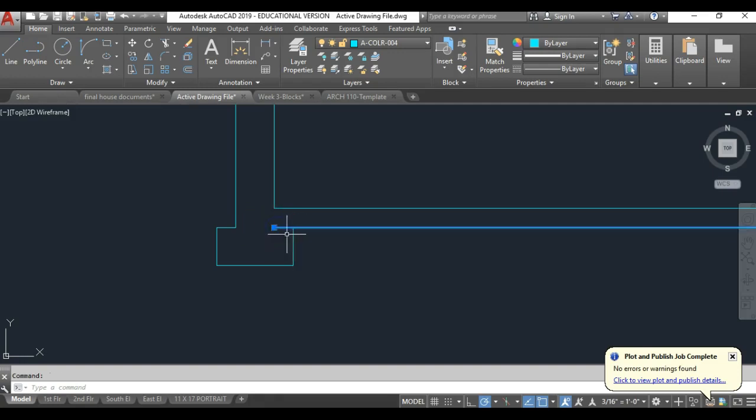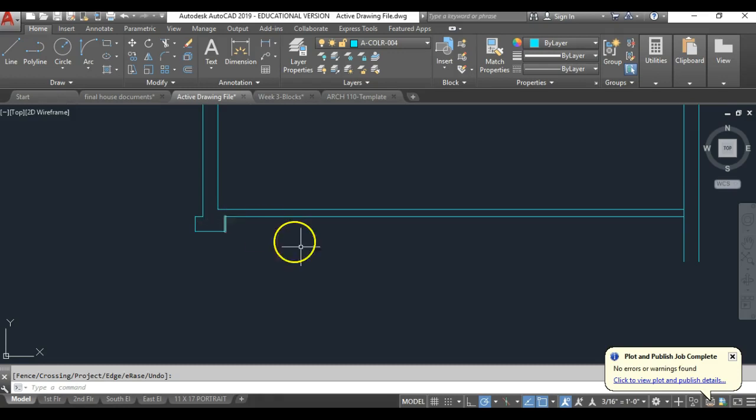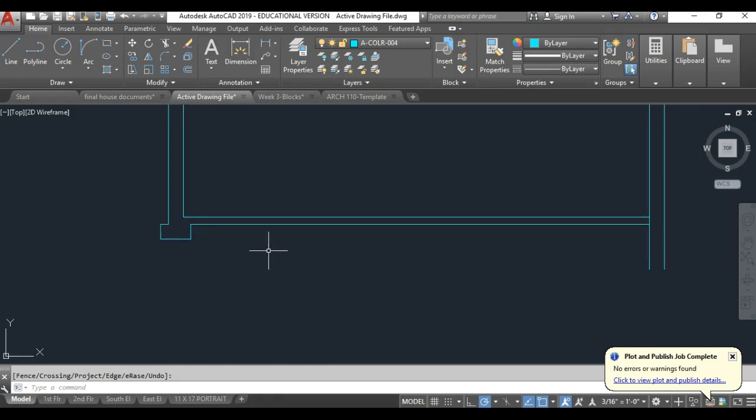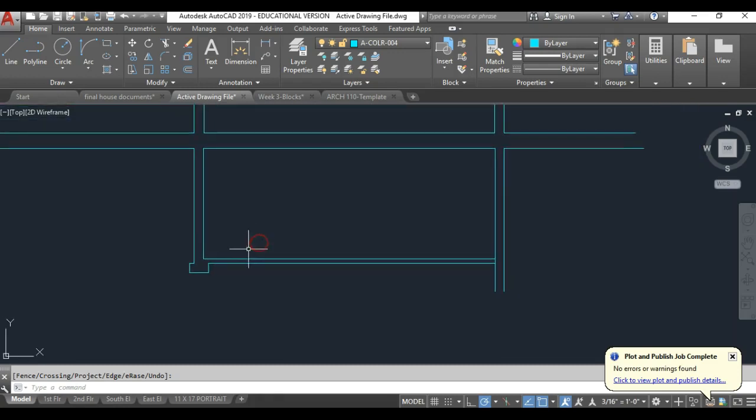And actually that was above that line. If that's the case, I can go back to trim. If you have 2 lines there like I did, hit trim, hit enter, and trim that away. The line that couldn't be trimmed was above it, so it was preventing me from getting it on the original trim. It's perfectly fine there. So I got that footing there.